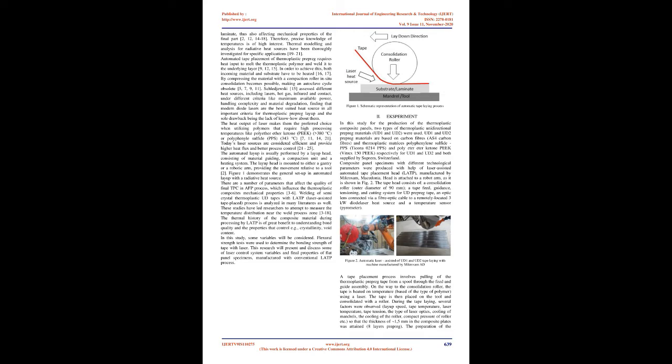The recorded temperature and pressure profiles are fed into a bonding model to predict the resulting strength of the manufactured thermoplastic laminate. 2-5. The heat is used in all of these processes for different reasons, e.g. to adhere the material to a tool or melt the thermoplastic prepreg component. Different heating technologies have been investigated, including hot gas, infrared, contact heaters and different lasers.